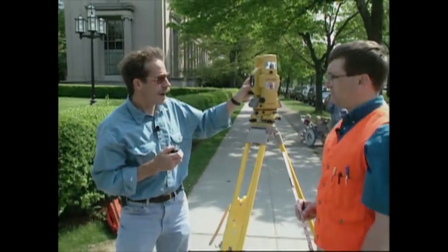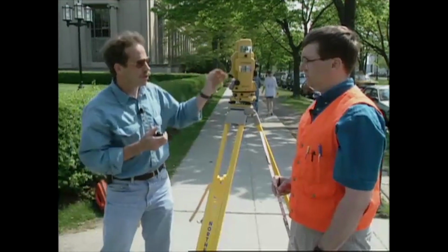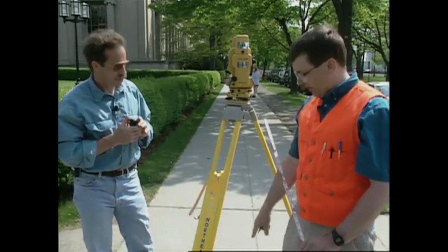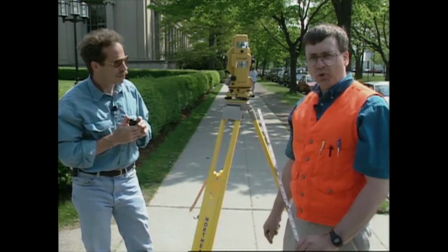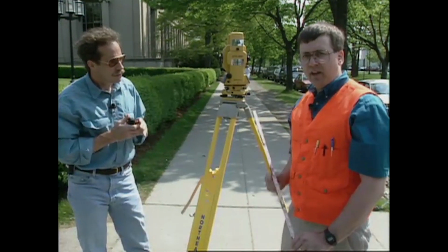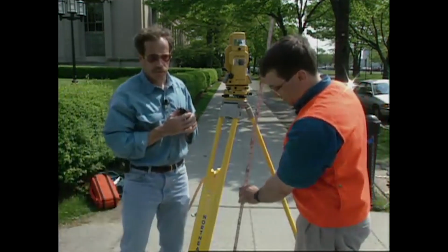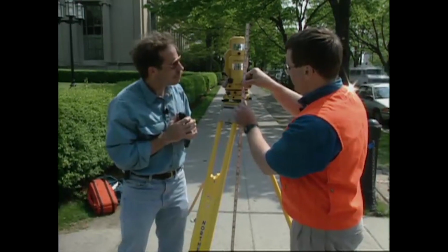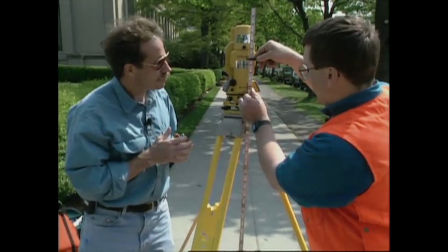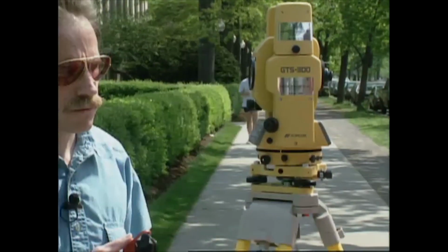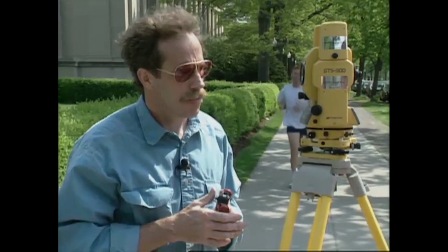So Ken, what we need to do here is find the height of the instrument before I go up in the dome to set up the prism. Yes, as we mentioned earlier, we established an elevation of our reference mark with relation to mean sea level datum, and that was done via differential leveling techniques. We've established an elevation of 10.02 feet on the reference mark, and what we will do is measure up with the ruler to an index mark on the instrument, and we're measuring 5.36 feet above the reference mark, which establishes an elevation of the instrument of 15.38 feet above mean sea level.